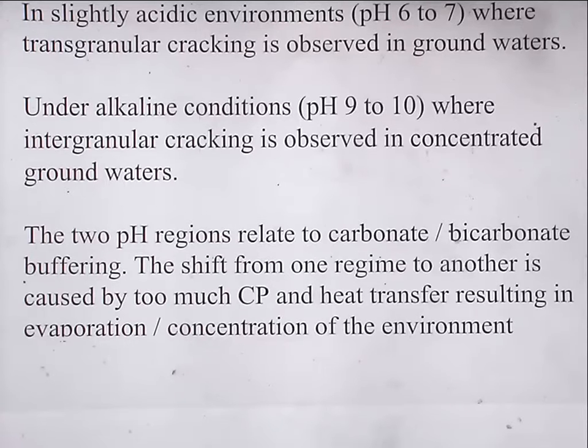They're not really corrosive, not like acid. You're not getting an enormous amount of corrosion. What you're trying to do is build up a passive layer on the surface of whatever the oxide is, so that you can then rupture that oxide film and get localized attack in one area. So it's got to be a balanced system.